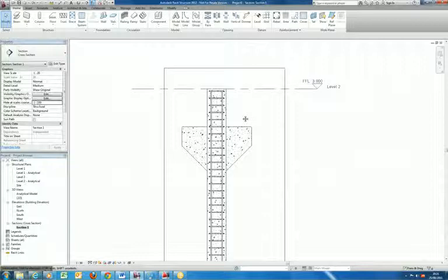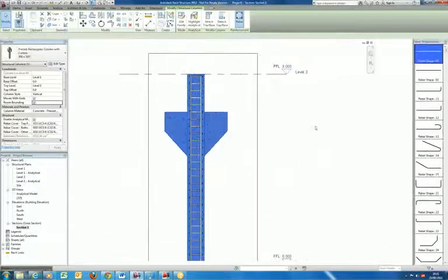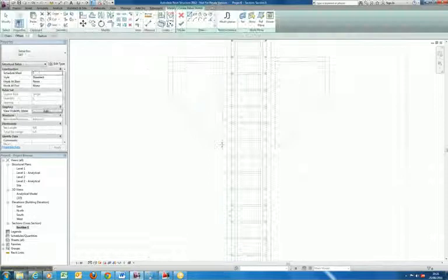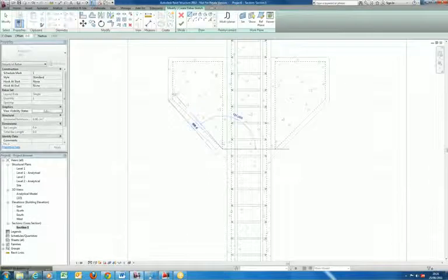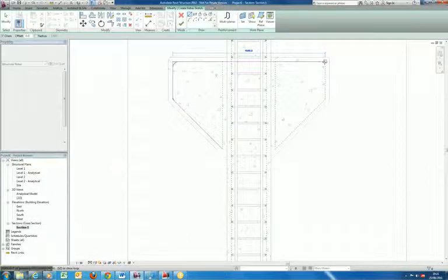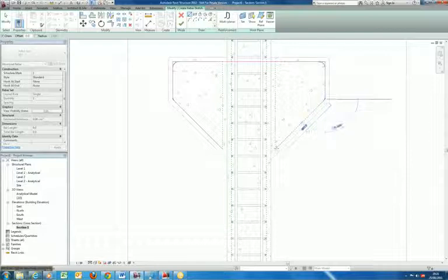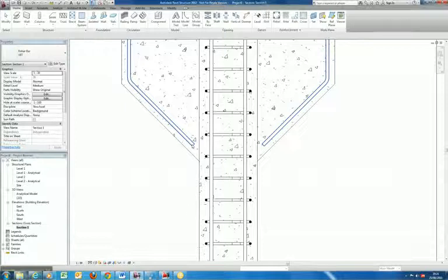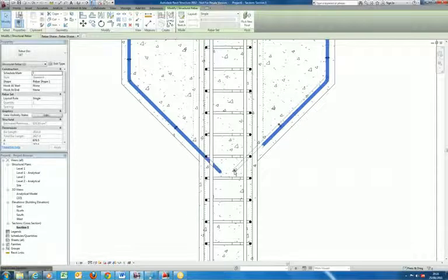Okay, let's add a custom bit of rebar in here. So again, we'll go back in the rebar. This time we're going to sketch it, and we'll keep it as T16 bars and pop this round, finish it out. The shape's in. What we can do as well, we can simply drag that down, and I'm going to distribute that throughout the column.